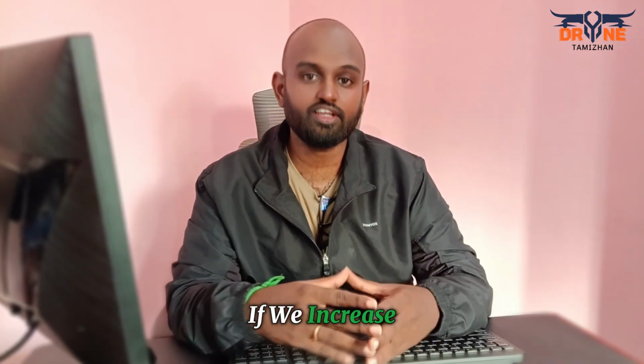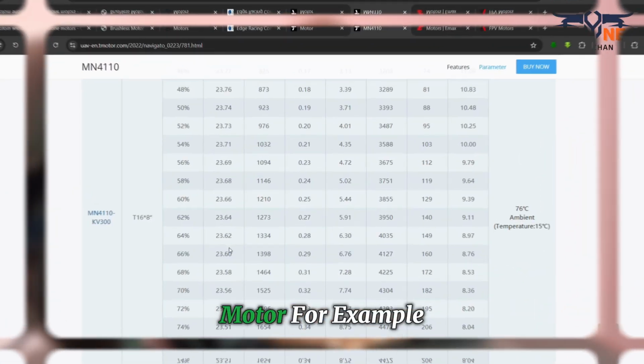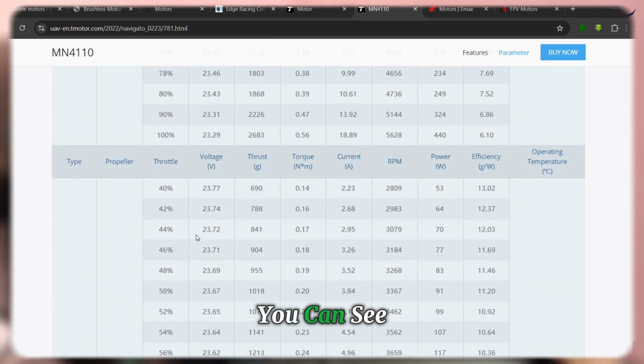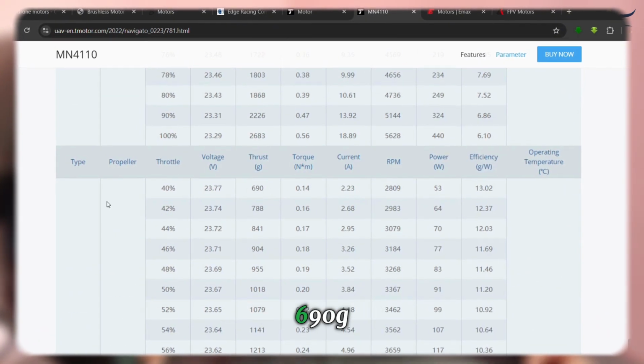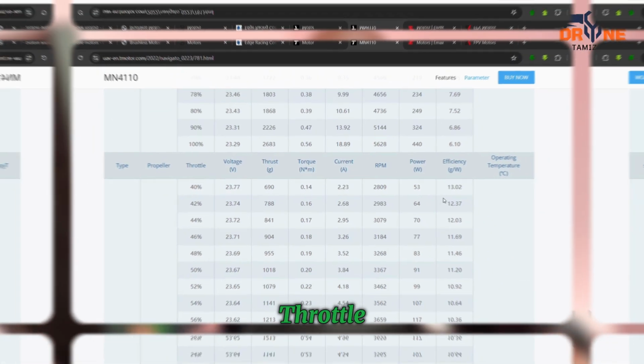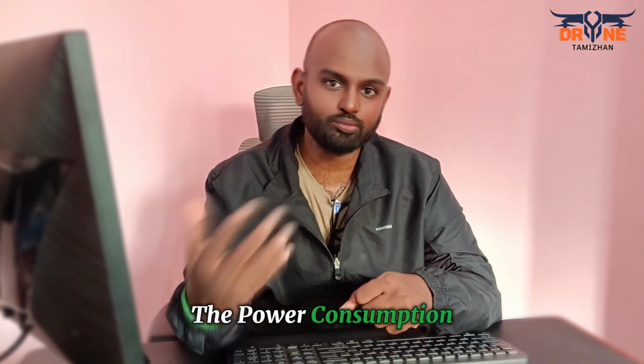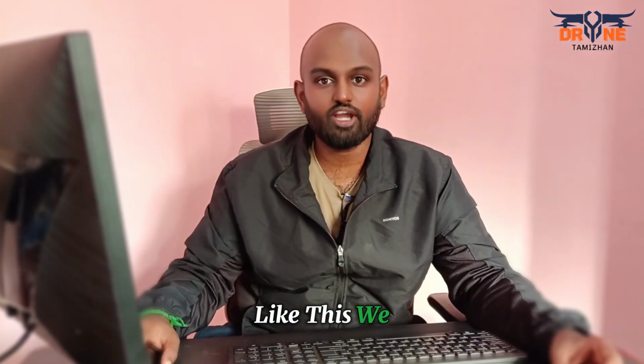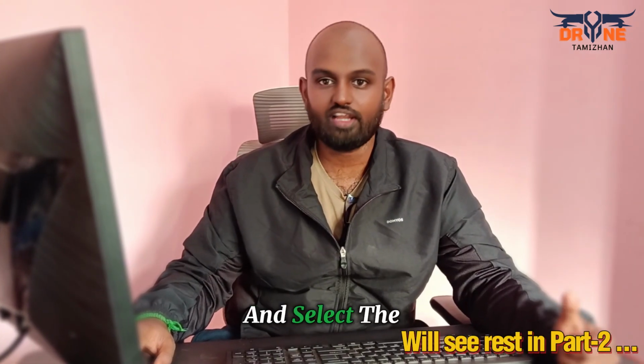What will happen if we increase the propeller size for the same motor? For example, if I use 17 inch instead of 16 inch, you can see here in the thrust chart, it is giving 690 gram thrust at 40% throttle, which is 60 gram higher than earlier. But the problem is the power consumption is increased by 2 watts and the size of the drone also will increase. Like this, we have to compare all the parameters and select the right one.